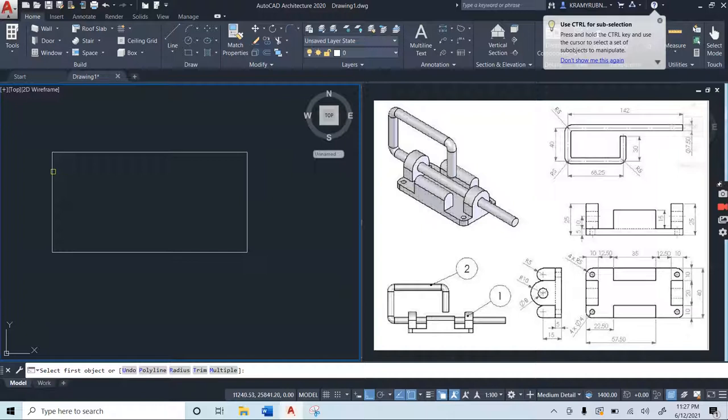Now all we have to do is to click on the lines that form the corner. So I have filleted 1 corner. Let's go ahead and fillet other corners. Now the 4 corners have been filleted like our model. The next thing we're going to be doing is to put in our 4 circles that will indicate the holes in our base. Now these are circles of diameter 4. Those 4 circles share the center of our curves.